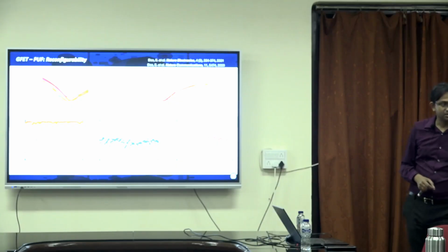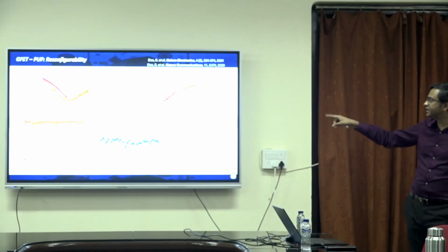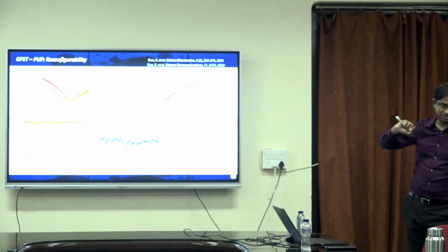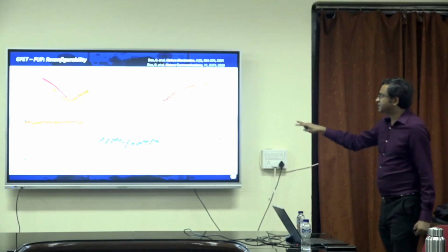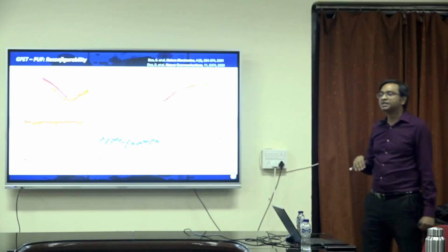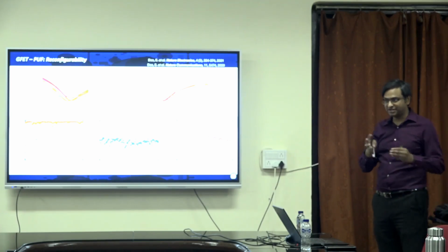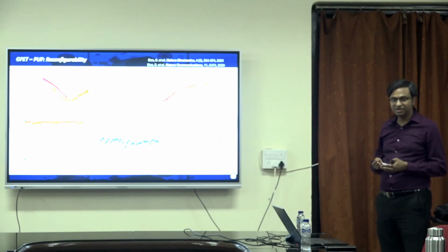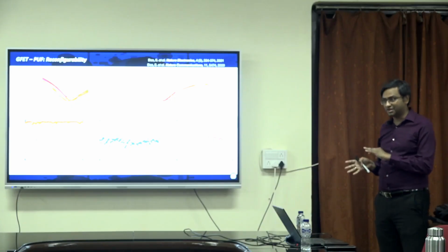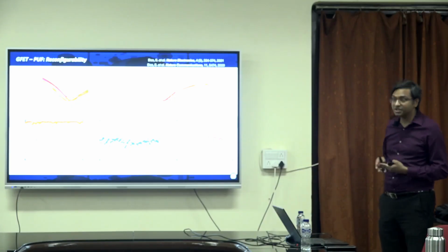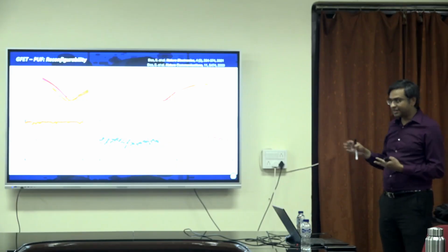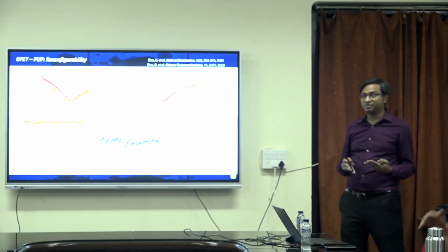You can change both the voltage magnitude or the pulse duration to program the memristor into different states. But the take home message is you can actually get reconfigurability in a PUF, which is not possible with silicon PUFs, because silicon is not a memristor material. So that's the advantage of 2D material, because otherwise you will say, why are you doing it with 2D material? The idea is that 2D materials give me this opportunity of reprogramming the device.